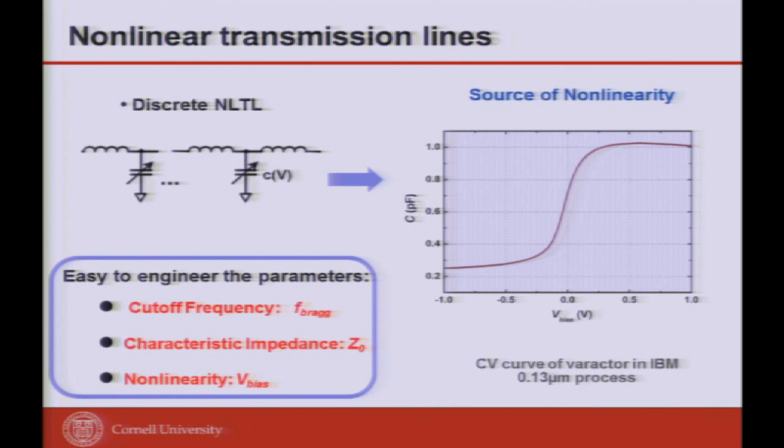Is that you put these discrete nonlinear capacitors as part of the transmission line. It's like your big L and one C as a discrete element for that narrow band thing. I distribute it to a traveling wave. And this is something that has been studied for 50, 60 years, called the KdV equation, these soliton circuits and all the things behind it.